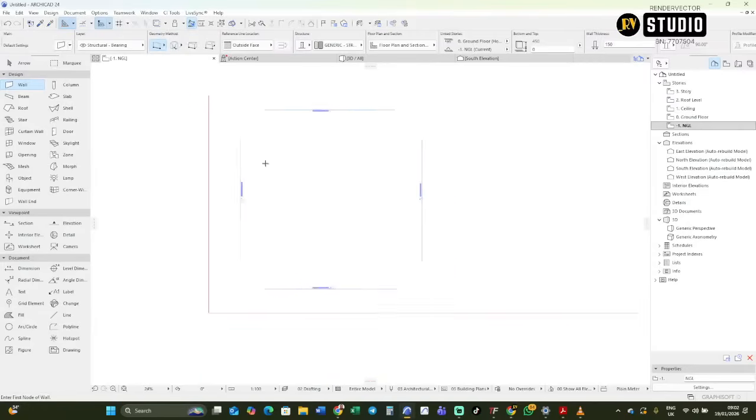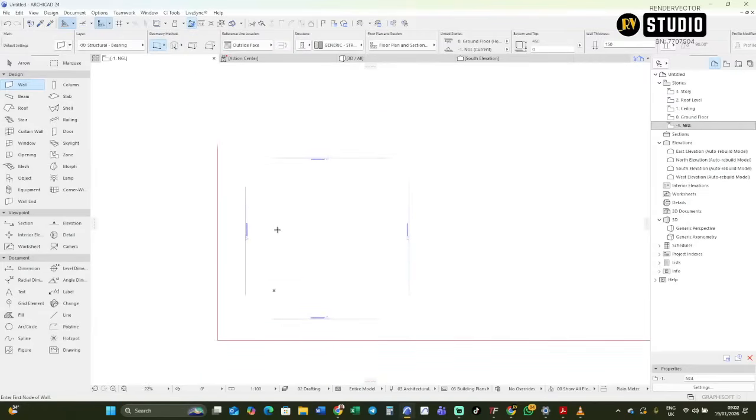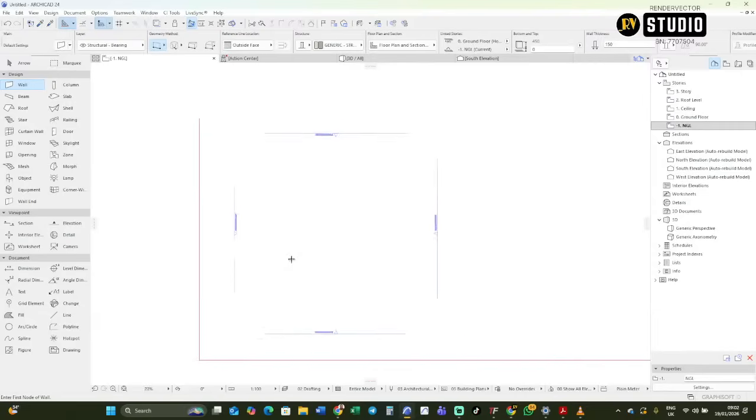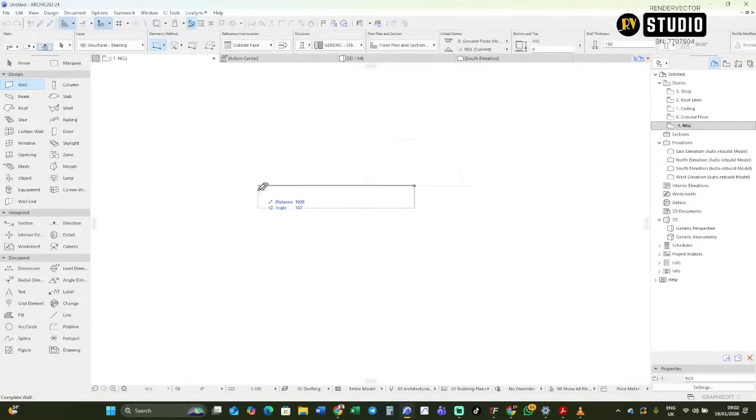Let's be dropping it single. Let's be singling them out one by one. And when you drop your wall, when you get closer, zoom in and drop your wall, you see that black line on top. The beginning of the wall, once I left click and move, you see the darkest line here, so it's at the side of the wall. Once you click on the wall and hold it, you see this blue line here, where the nodes are. You get that node.